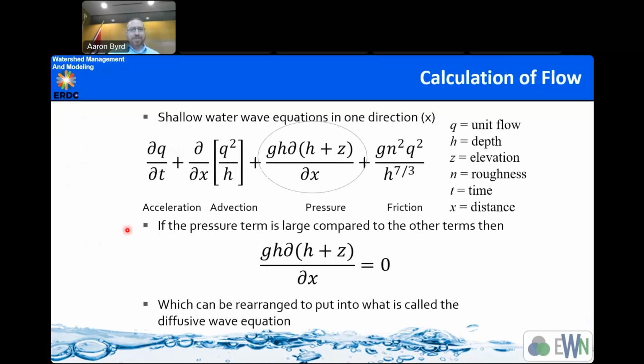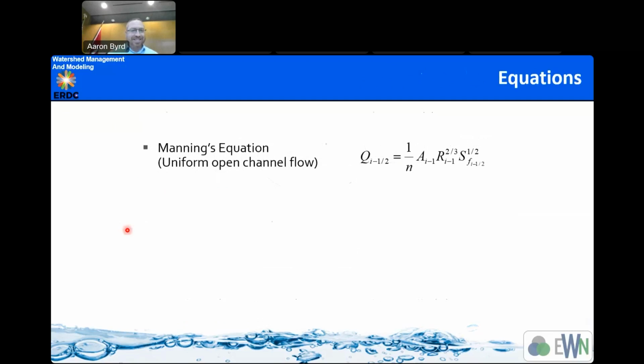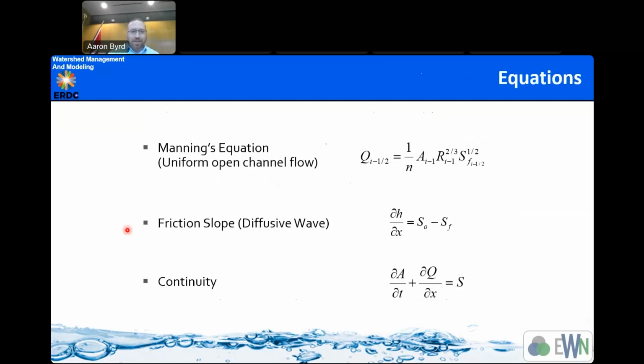This should look familiar. I'm going to skip it. Same equations as the overland flow. It should look very, very similar. What we need is cross-sectional area. In the overland flow, it's a very thin layer, but here we have an actual channel, right? Channel roughness, channel bed slope: S naught is your bed slope. Your delta X is your distance, your computational element distance, and the time step.